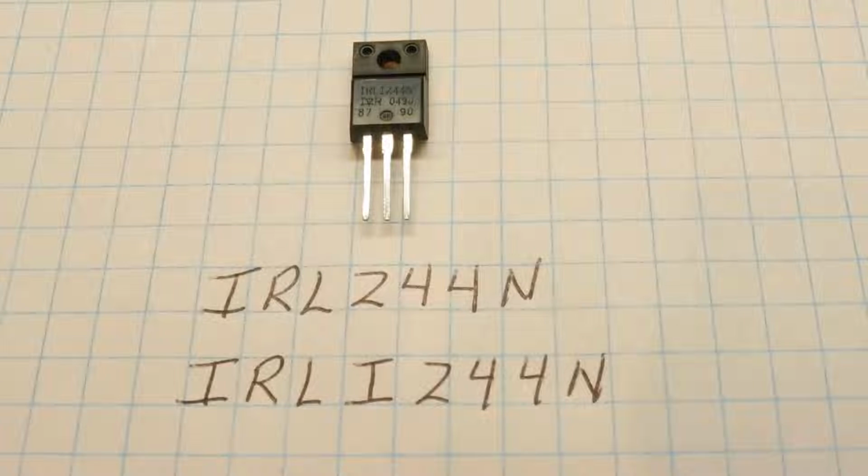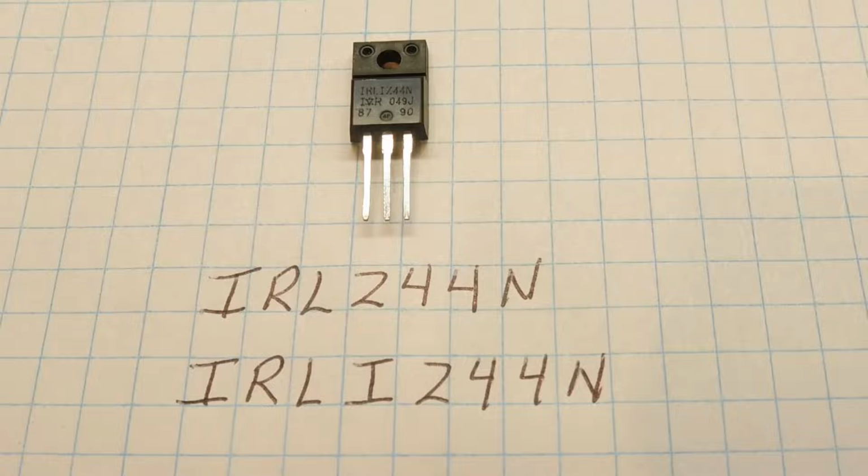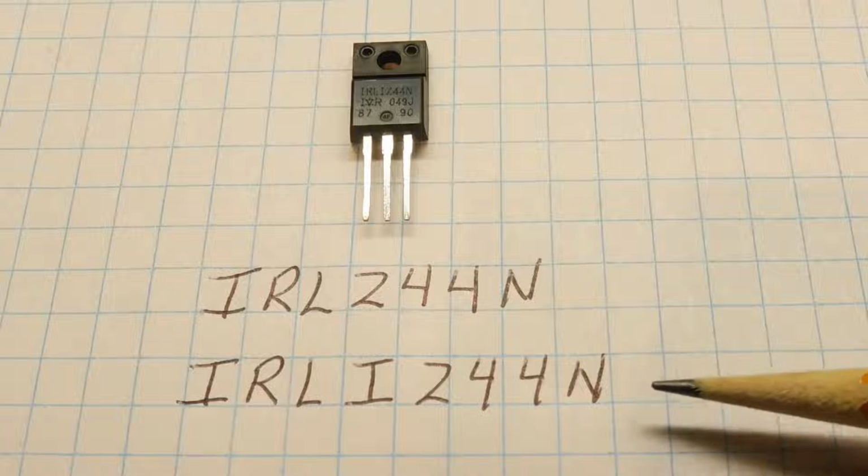Okay, in this video, we are going to look at building a MOSFET bootstrap circuit. Now there's two power MOSFETs that I use in my projects and that I stock. One of them is the IRLZ44N. Now the L in the part number means logic level. So we could drive the gate to source with the output of a 5-volt microcontroller, and we could turn this MOSFET fully on.